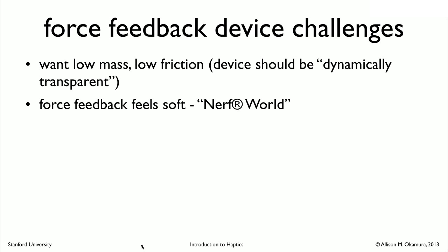Another point is that in impedance type haptic devices, the force feedback tends to feel soft. In the fourth week, you'll start to render virtual springs, and you'll see that you're going to be limited in how much stiffness you can display through these environments. This can happen because the motor saturates, so our motor is only so powerful.